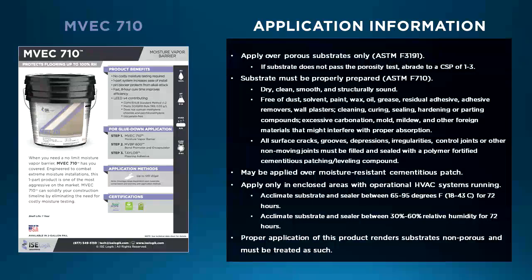Dry, clean, smooth, structurally sound, of course free of dirt, solvents, paints, wax, grease, etc. It may be applied over moisture-resistant cementitious patch. So if there are uneven areas, surfaces that you need to level out, you can use a moisture-resistant patch.